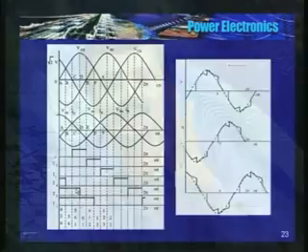So remember, if three thyristors are conducting, I need to use IA plus IB plus IC is equal to 0. Load is resistive. So till the phase voltage becomes 0, the equivalent circuit which consists of three thyristors is valid. The moment one of the phase voltages becomes 0, the thyristor which is connected to that phase turns off, and till the new thyristor is triggered, only two of them will be carrying current. And this principle you need to use to analyze three-phase AC voltage regulators. It is not very straightforward as compared to a three-phase AC to DC bridge rectifier. That is the reason I told you this is not very straightforward, but then it is not very difficult either.